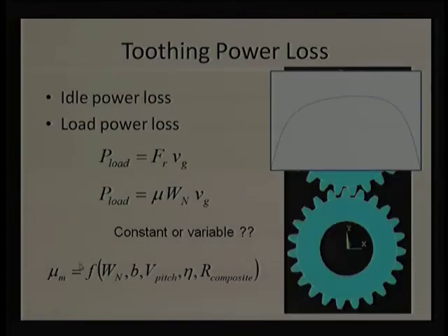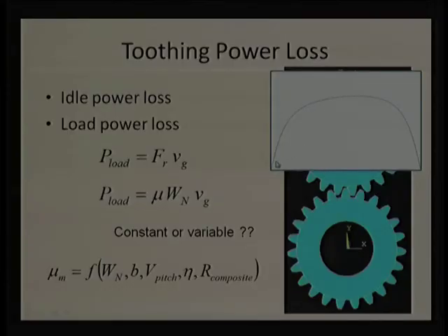Now, when we discussed normal load in a previous lecture, we mentioned the contact ratio. If the contact ratio is more than 1, that means for some part of the rotation 2 gear tooth pairs are in contact, and because of that there will be a change in the load. Quite possibly during engagement the load slowly increases, reaches a steady value, and at the time of disengagement the load starts decreasing again. So one gear tooth is going to experience this kind of load variation.